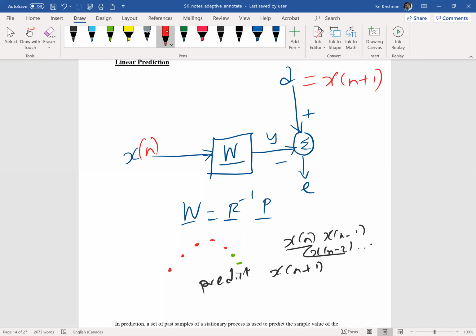Now the desired response, previously we didn't have a good idea about the desired response, but when we did the adaptive noise cancellation, we configured the desired response in a way that helped us get a better fetal ECG representation. Similarly, in this prediction concept, it's very simple and straightforward: we have made the desired response be the signal itself, but its future sample.